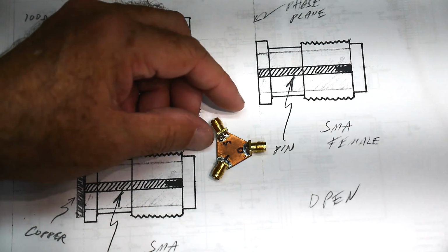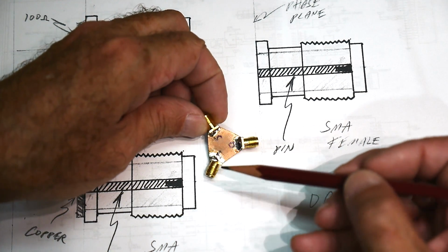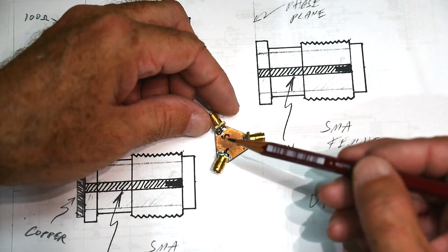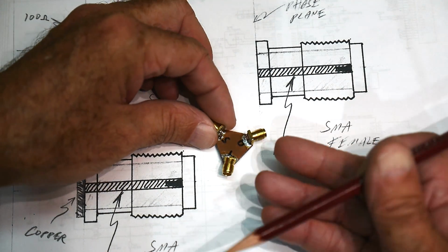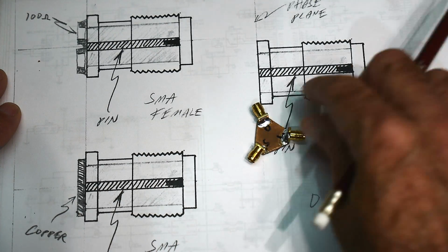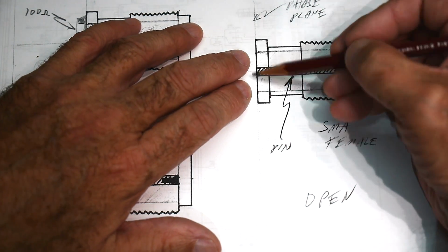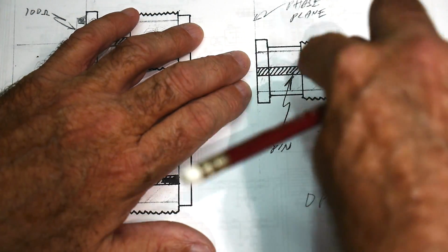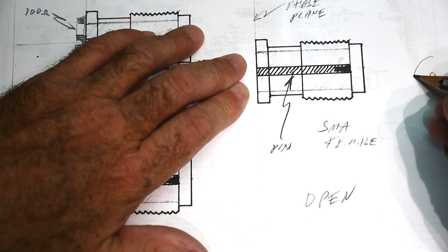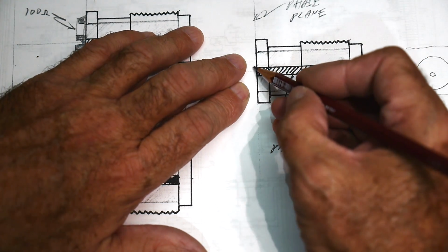I have a video showing me constructing this set of cal standards as an open short load in female SMAs. The ones that you get in the kit are male, but sometimes you want to be able to calibrate with females. And so I constructed these, and I'll show you my thought process and why I did what I did to make these things. So these are cross sections of the little SMA connector blown up. And so we take one of those connectors, and there's nothing on the back side. So if you looked in this, you would just see a center conductor, and then you would see a plastic insulator, and then the rest would be metal. All right, that's what you would see here.